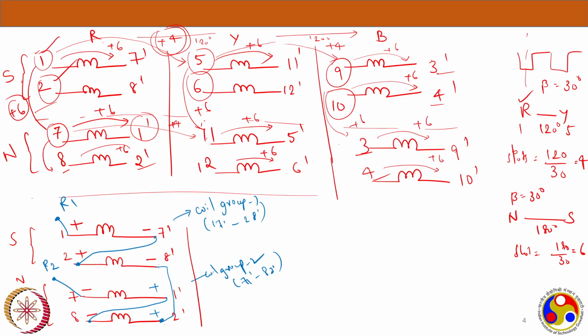So that's how you should be careful while connecting these coils across the poles. So make sure that the minus is going to plus terminal only. Then only you will get a maximum, or else the entire voltage will get cancelled. That also we will see in the phasors clearly. But I am telling you, if you want to get an additive voltage, connect in series, but to the opposite terminal, so that the entire voltage will be additive.